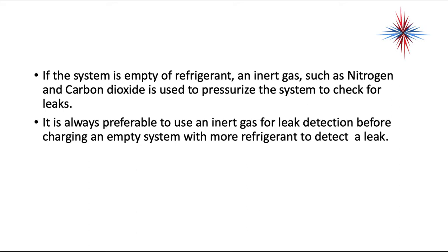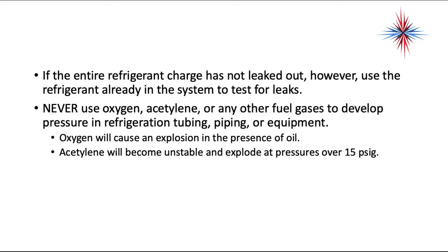It is always preferable to use an inert gas for leak detection before charging an empty system with more refrigerant to detect a leak. If the entire refrigerant charge has not leaked out, however, use the refrigerant already in the system to check for leaks.